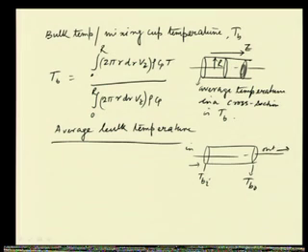That means T b I is the bulk temperature at the input, T b O is the bulk temperature at the output. Therefore, the average bulk temperature, T b average, is usually the arithmetic average, and that is equal to (T b I plus T b O) by 2. That is also one important piece of information that we should know.